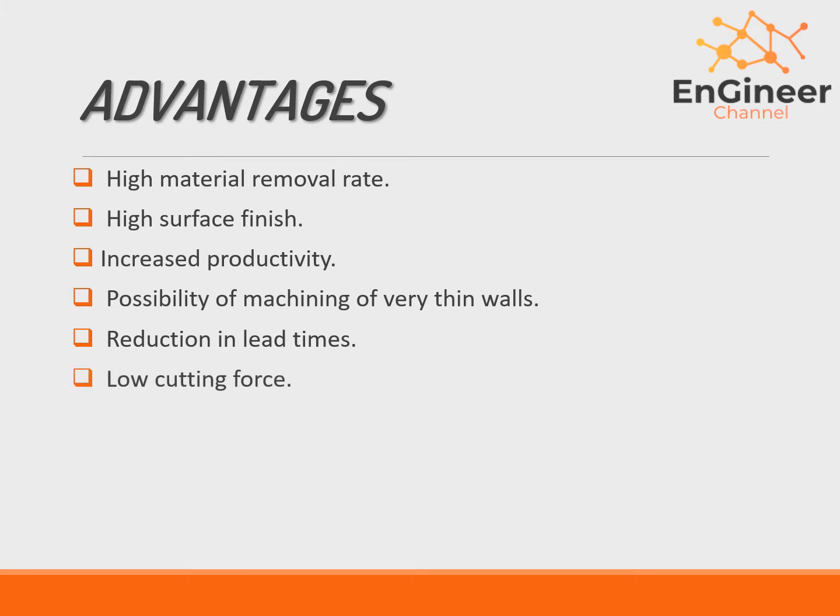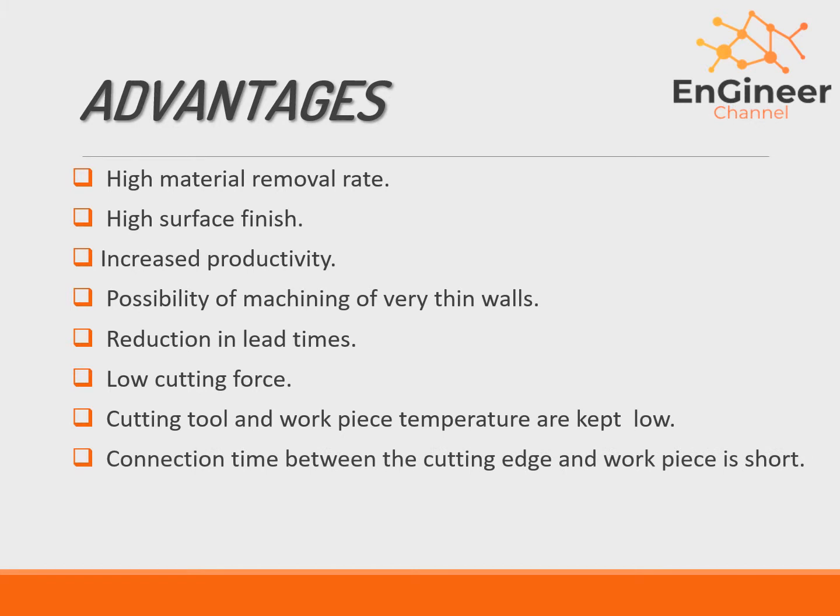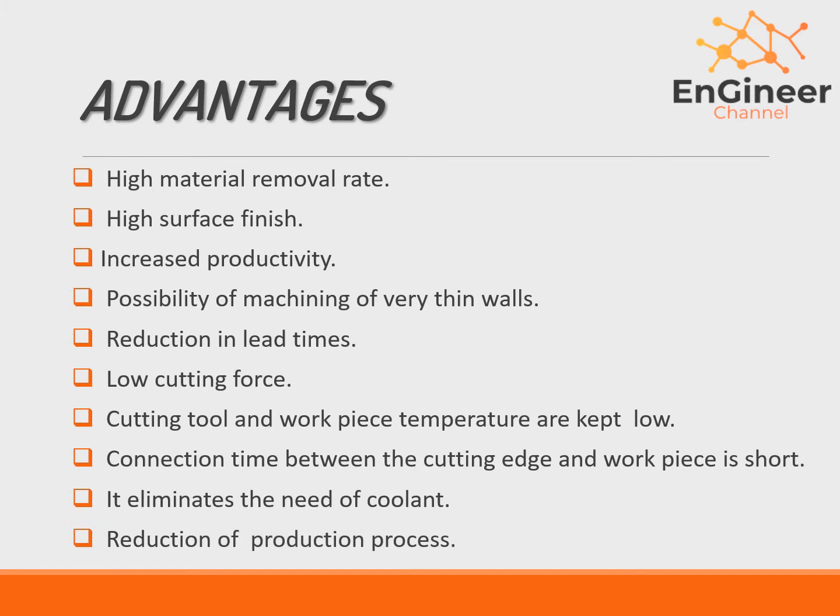Low cutting force. Cutting tool and workpiece temperature are kept low. The contact time between the cutting edge and workpiece is short, and it eliminates the need for coolant. And finally, a reduction of the production process.